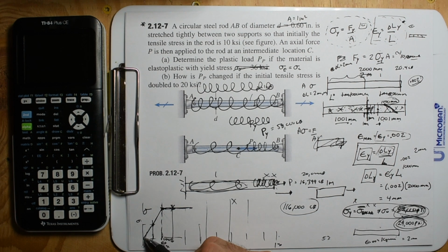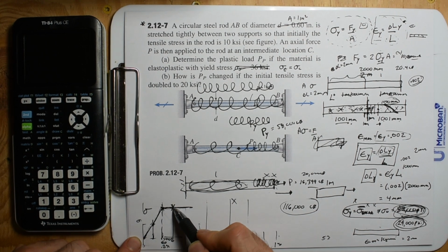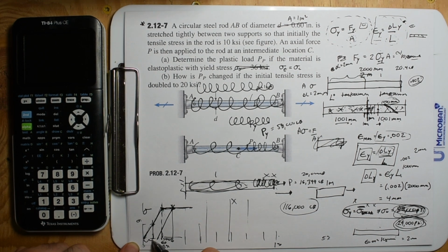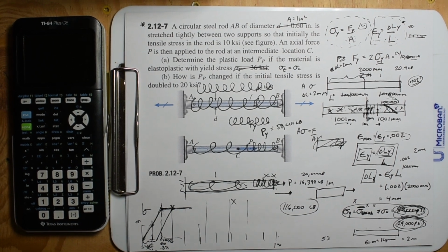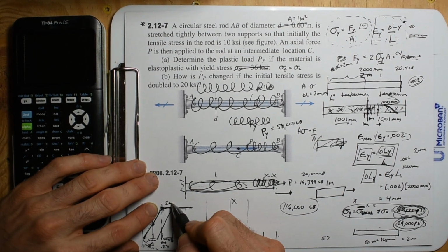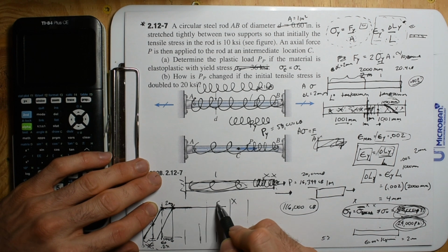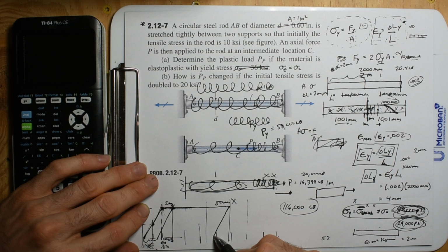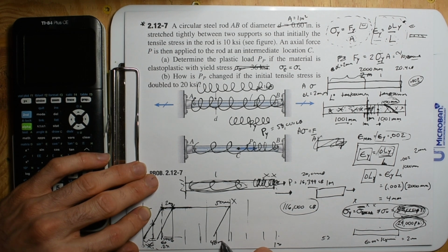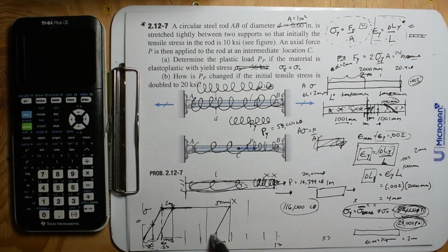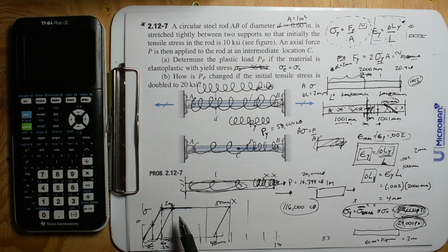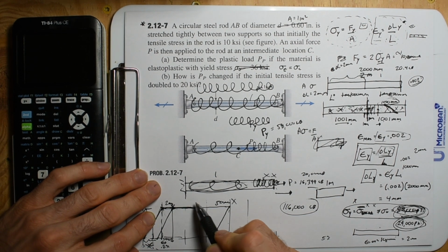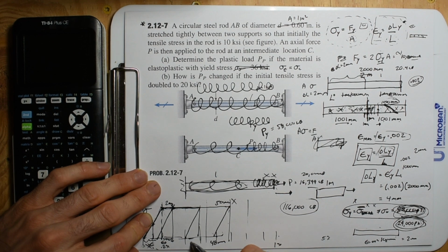It's within this elastic range. It hit the ceiling, but then went back down to 0. The second you go plastic, no, you permanently elongated it, whatever that was. And like I said, this is 2 millimeters of plastic. You could get up to 50 millimeters of plastic, still not have it break, let go of the tension, and it's going to go back to 48 millimeters. See, so a lot of people don't put numbers on these, and you know what I mean. If you stretch it 10 millimeters and then back it off, well, it's going to back off 2 millimeters.